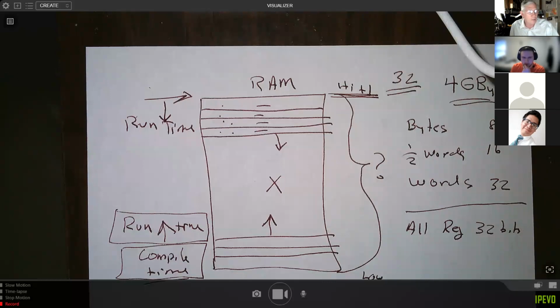Now they do have an RTOS system available, which you can use, and then it will provide some surveillance. It will compartmentalize memory and keep threads from interacting with each other and things like that. But most RTOSs are fairly limited in their supervisory powers, because you want it to be lean and mean so it can be real time. That's the problem with Windows. Windows is so bulky, it can never be real time. So you can never schedule an event to happen at a specific time in Windows. It'll never happen that way. It's going to have latency.